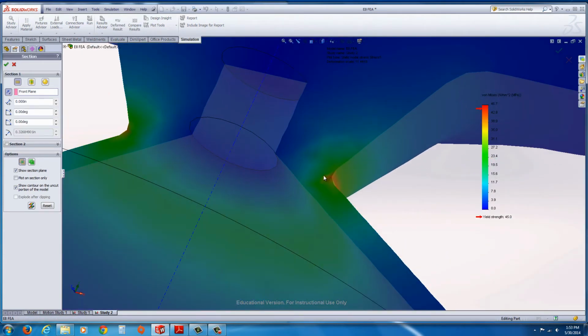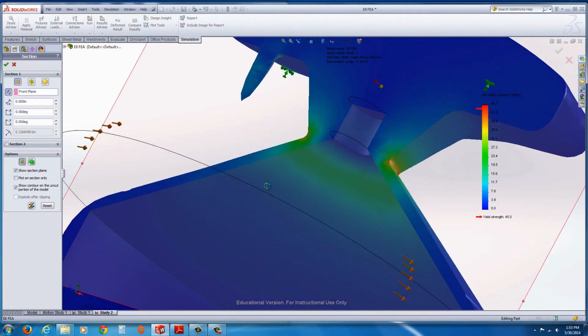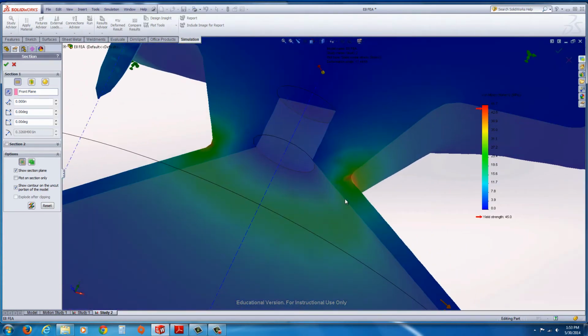In this case, the design is really not that great, because if you look at the point which actually the red is bleeding into here, it's actually going down. Maybe it's not the best design. This should maybe be opened up. Regardless, the intent here is to really take a look at what's going on. The red is not bleeding all the way through. Thus, at 20 pounds, this is not functioning as we'd hope, because we want it to be less than that. So obviously the design needs to be changed, or the material can be changed as well.